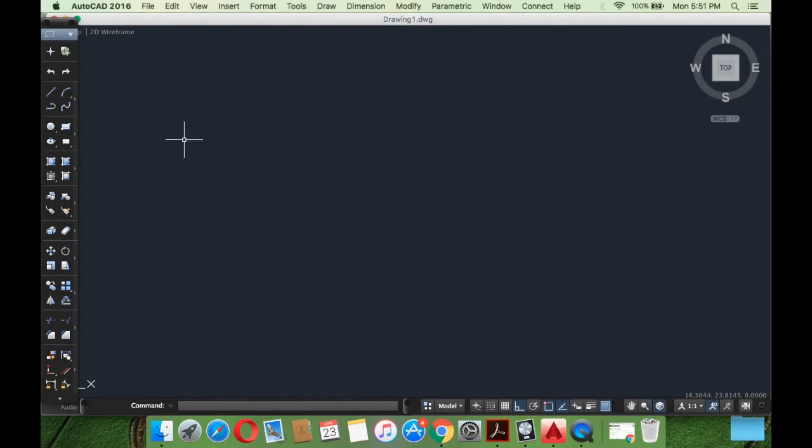Now you don't actually need the baseline. You can draw any particular line, and it will always be drawn with reference to the x-axis. Suppose I want to draw a line, and I've initialized the command by giving the first point. I give it a length of, since we have been drawing really small lines, 1000 millimeters at an angle of 60 degrees.